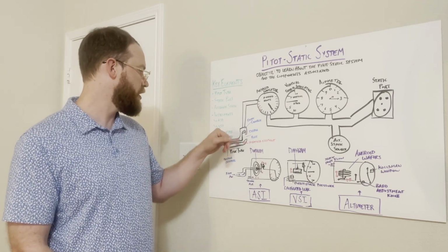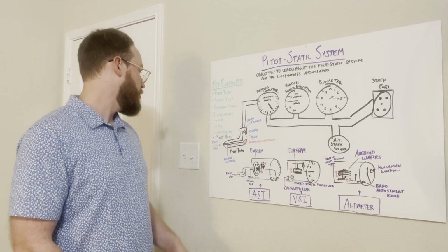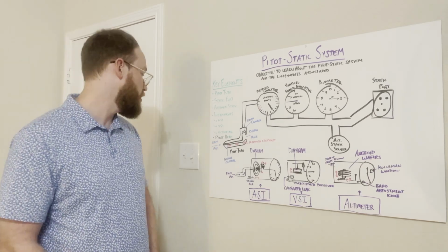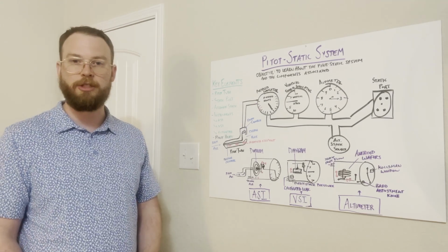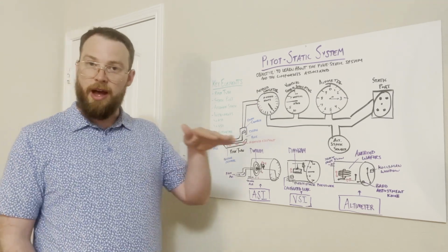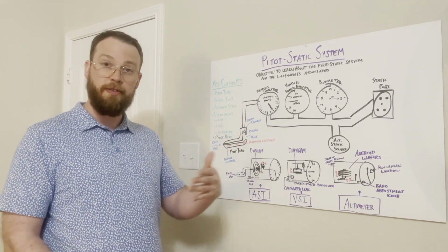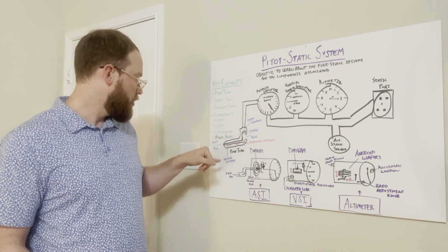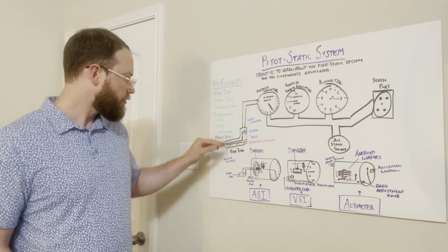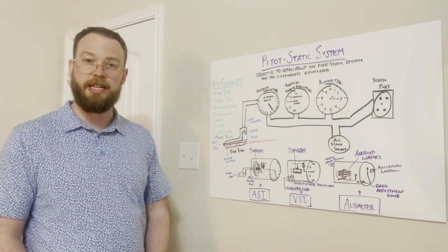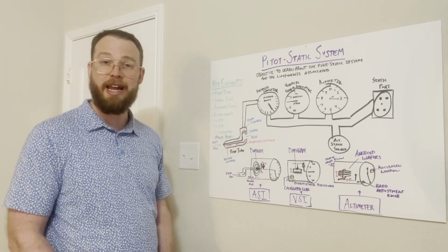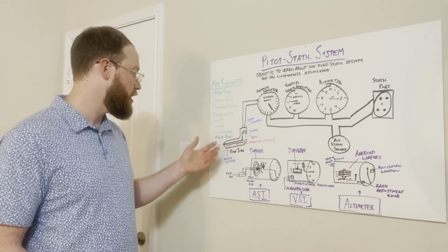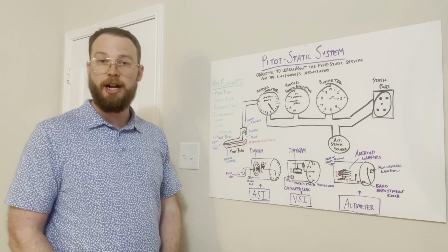So here's an illustration of our pitot tube. What we have is a diagram of what happens inside the pitot tube. So we have ram air, which is basically the air that, as we fly through the air, is going to go into our little pressure chamber here. Kind of on the outside of that, but still inside the structure here, is the static chamber. And basically the difference between the two is going to be our measurement of our airspeed.